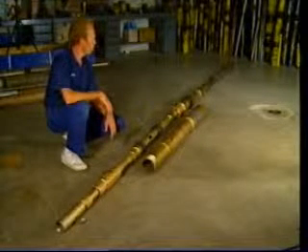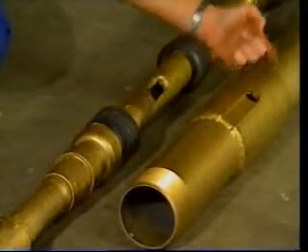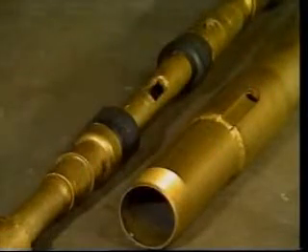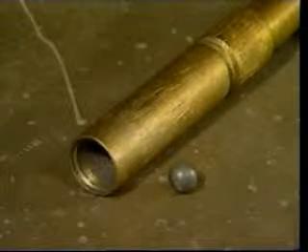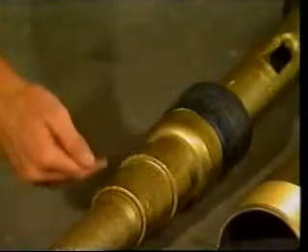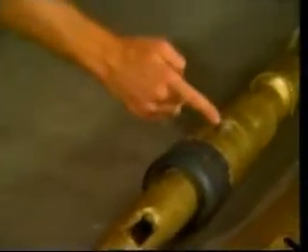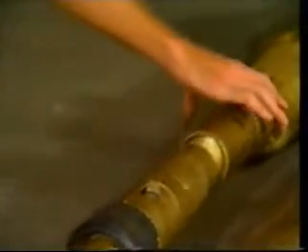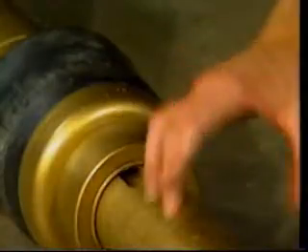The sand-laden fluid is pumped down the work string and flows out the gravel pack port, through the port collar, and into the open hole outside the screen. Fluid returns through the screen, into a slotted bull plug, up the wash pipe, through the check valve, and the 2-cup straddle tool, out the lower bypass port, then into the down cup tool, out the bypass port, and up the tubing casing annulus to the surface.